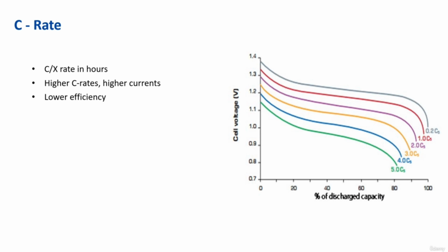Let's have a look at how a typical charge and discharge curve schematically looks at different charge rates expressed as C rates. The voltage during charge increases when we apply larger currents, and it decreases during discharge. This is the consequence of the internal resistance of the battery, the origin of which will be discussed in the next lecture.